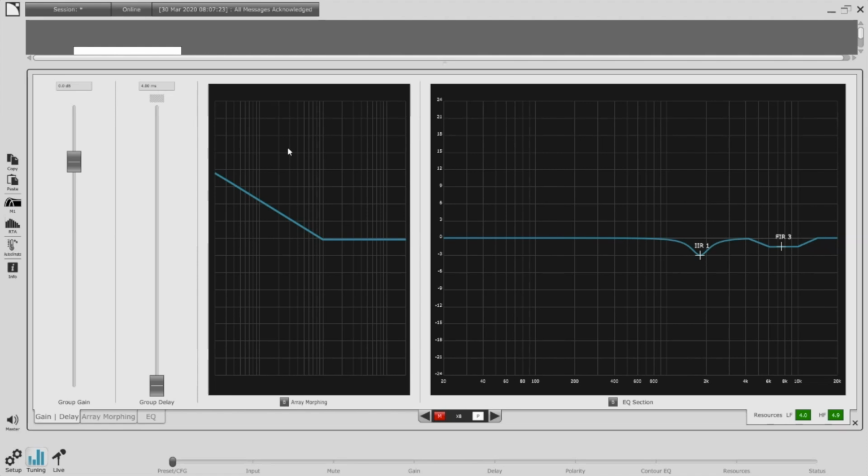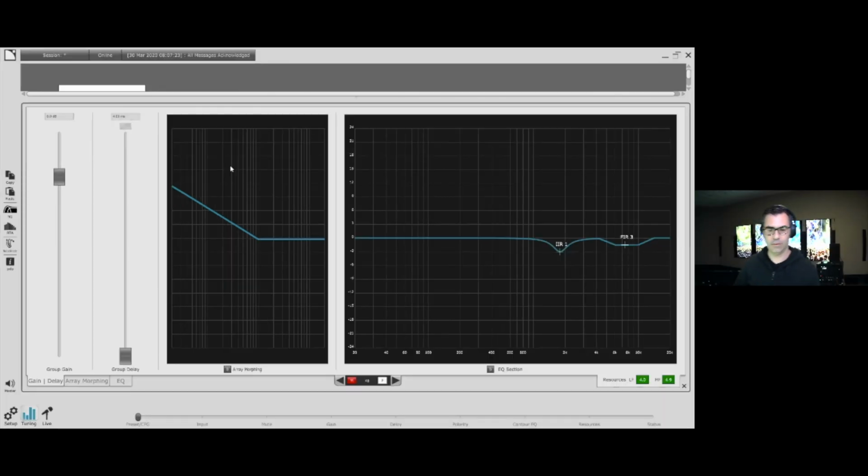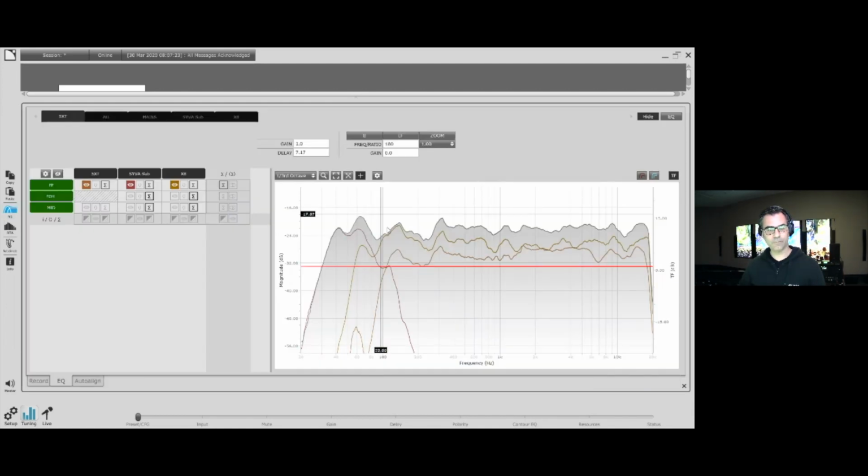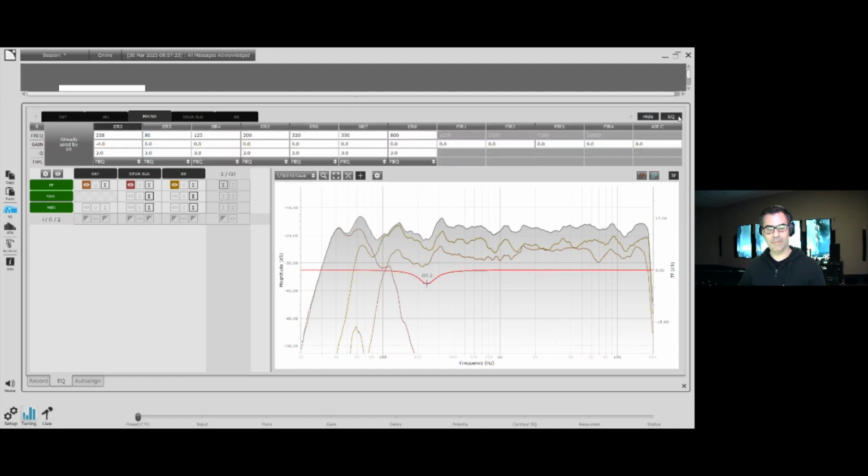And this is bidirectional. So what's really powerful about this is in the middle of the show, if you are mixing an event and you realize, you know what, on this X8 or the main system, there's just a little bit too much 250 hertz, maybe the audience has changed the way it sounds, I can pull some of that out. If by chance I go back into M1, I can see the effect of that EQ on the mains, and I can see what it's done to our transfer function. Oh, I see it. Maybe my problem wasn't at 250. Maybe my problem was more like 310 hertz. Maybe it was that bump that was bothering me. So this is all bidirectional from within LA Network Manager, the workspace, to the interface of M1, the measurement portion of the software.